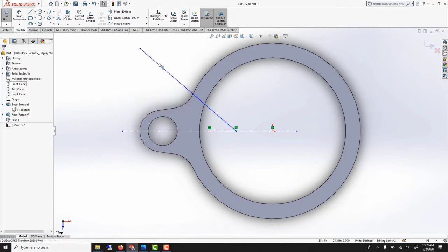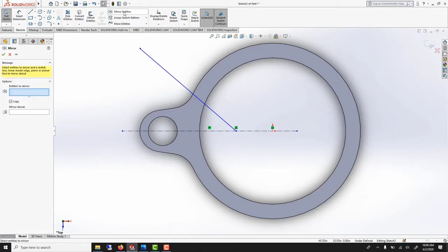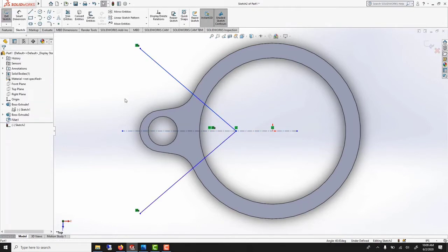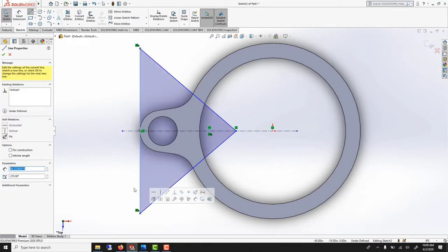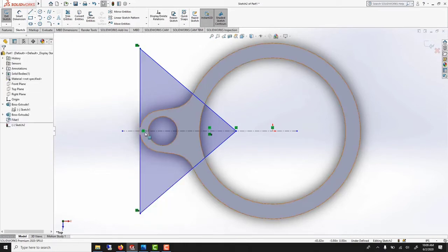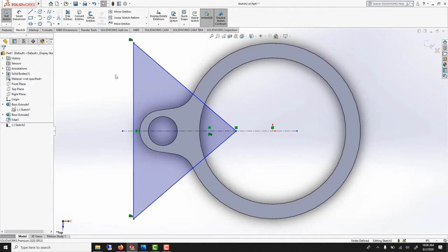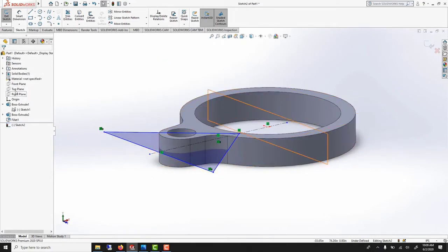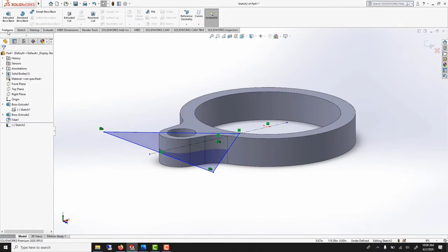And this we're going to use to cut out. So I want to make this symmetric on the other side. Mirror, symmetry is this. And the mirror about will be this one. Then we can connect. So line, L. Voila. So as you can tell, it's touching a little bit. So you could just move that line a bit more. Voila. So we're in the center because we did it on the top plane. Extrude cut.